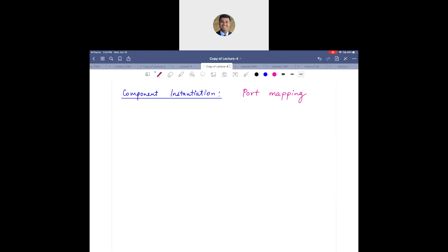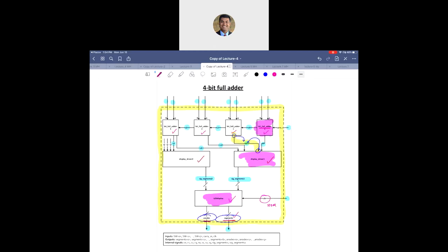And that particular step is essentially this. You have told the VHDL compiler what are the different components you are going to use. You have defined all the signals. Now what you have to do is bring in each piece of the puzzle and make all the connections.